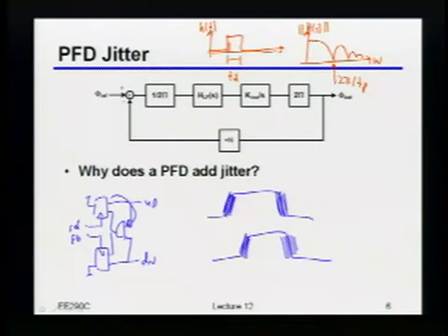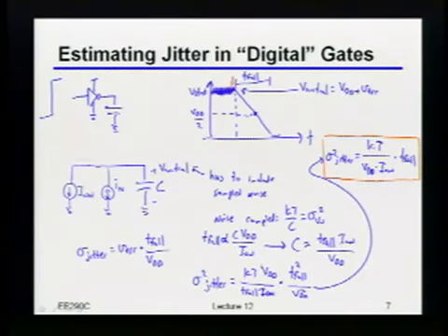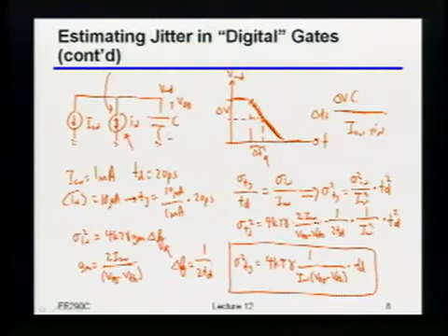Does that make sense? I had two questions. The first one is, why don't you consider the noise on the capacitor? Well, okay, you're saying why don't I include the noise that I sampled previously? That is from the inverter, right? This noise up here is really from the PMOS transistor, which was just quote-unquote holding the output. This noise right here is from the NMOS transistor when it's pulling the output down.